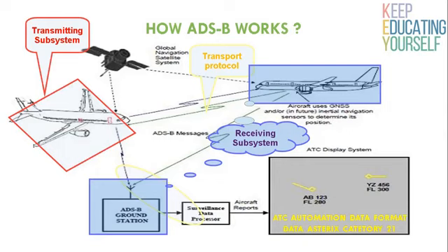The transport protocol can be VHF Mode 2 or 4, 1090 extended squitter, or 978 MHz UAT. A receiving subsystem that includes message reception and report assembly functions at the receiving destination. It can be another aeroplane, vehicle or ground system.